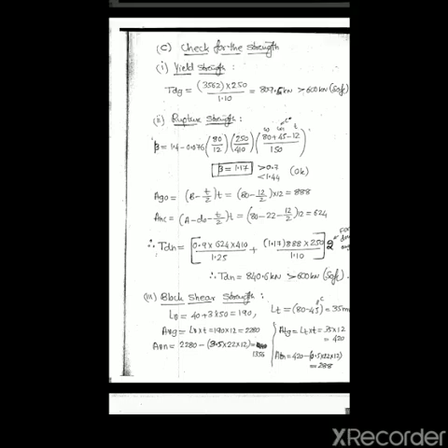Similarly, ANC, the net area of the connection, is (A or B minus D naught minus T by 2) into T. Now A is equal to B value 80 minus D naught. I already mentioned, always take D naught as the diameter of the hole plus clearance of 2 mm. So total 22 mm, minus 12 by 2, into 12 is 624 mm square.